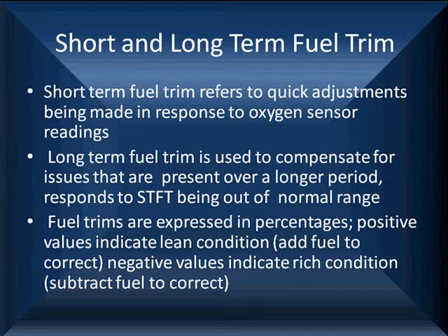Fuel trims are all expressed as a percentage. Positive values indicate a lean condition. We need to add fuel, positive. Negative values indicate a rich condition. We need to subtract fuel, a minus.